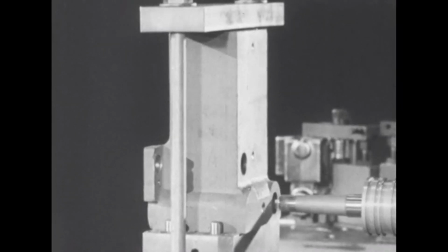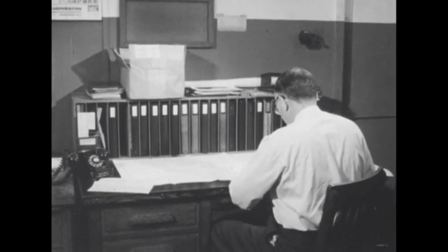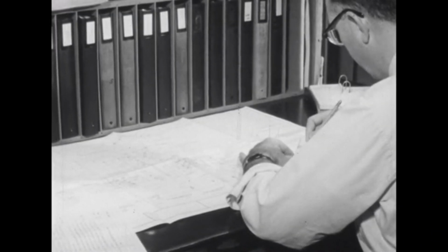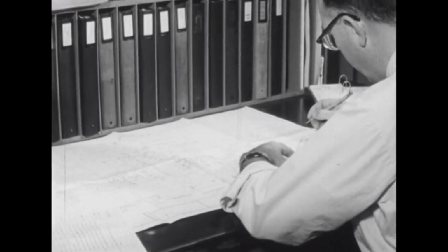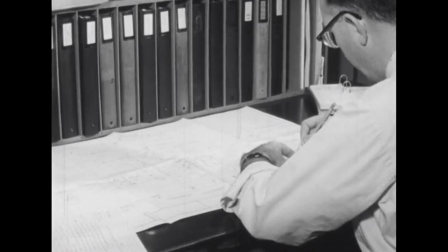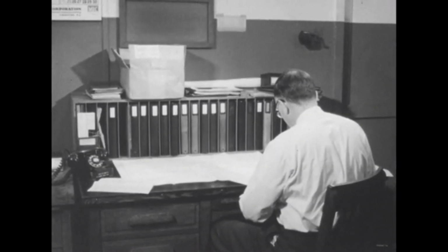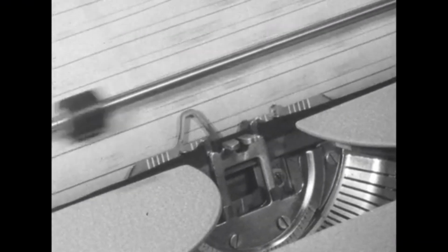As a first step to set up this machine for a new job, a process man analyzes the drawing and lists all operations necessary to produce parts in accordance with its specifications. Next, for each operation, he selects the proper cutting tool and determines the relative position of tool and workpiece, also the proper feed and speeds and type of coolant. Each of these items is assigned a code number, which is translated into holes punched into a tape.